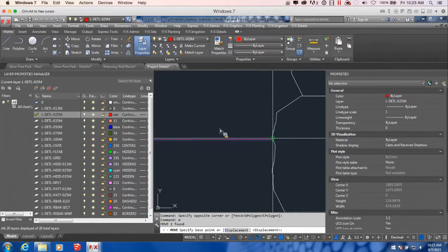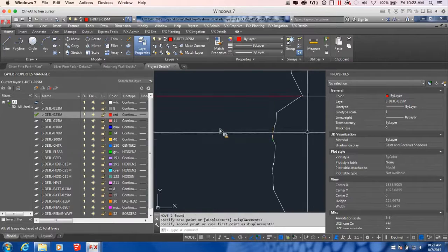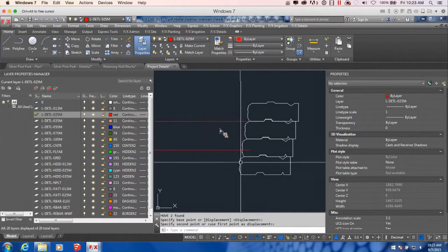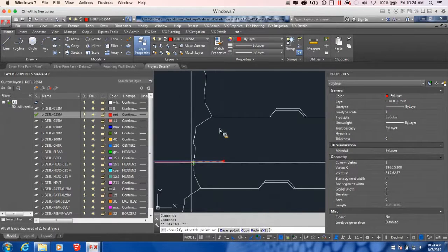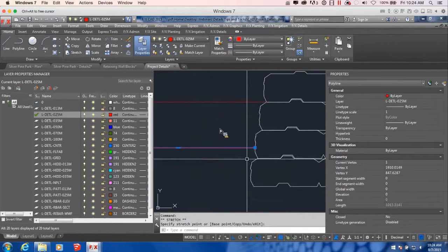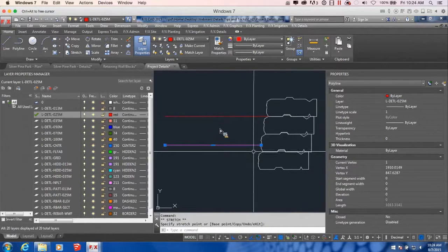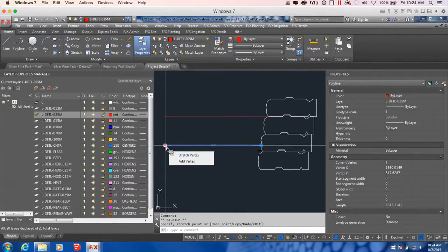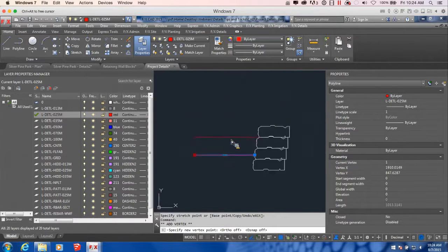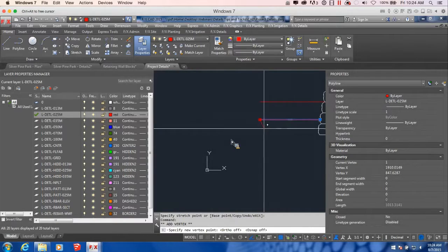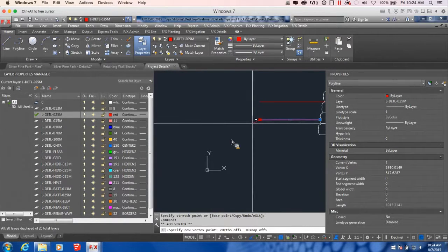So it's only 1 step tall from the top of the mulch. Great, so that's definitely dictating to me, okay, so that's going to be buried, perfect. I'll pull that in. And I'm actually going to add in a few more because I'm going to want the bottom of my playground to be a little bit sloped for drainage. So I'm going to add a vertex to this line. And we'll go here.